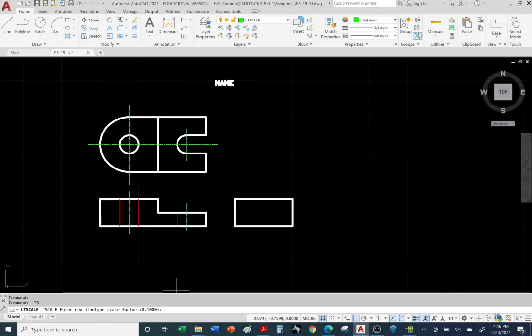So when you change the scale, I'm just going to move the decimal over. So instead of 0.100, I'm going to type in 1 and see what I get. I'm going to hit enter, and 3, 2, 1, enter. Did you see what happened to the scale? You blinked, so rewind the video so you can see that it did change the scale. It's like, that's too much. Let me go back to LTS.